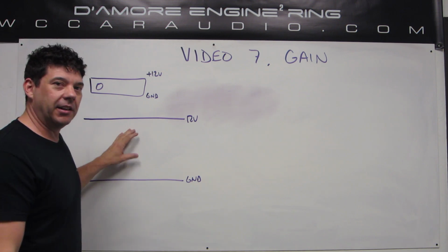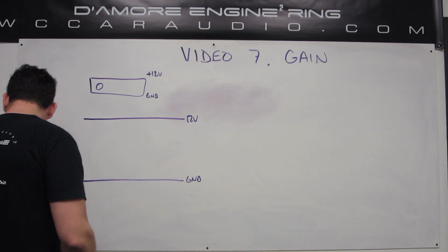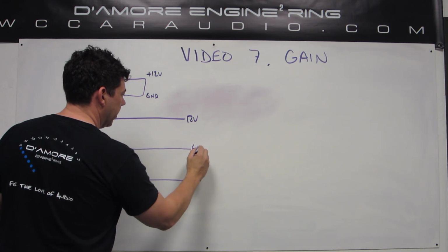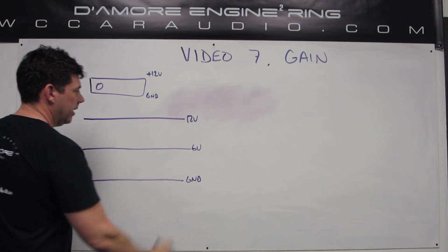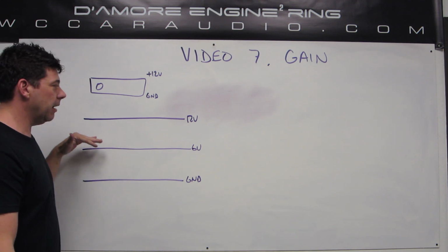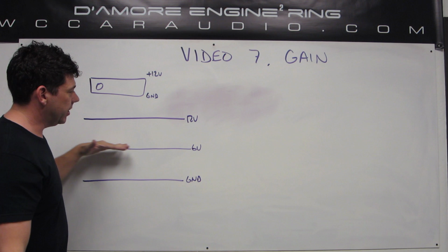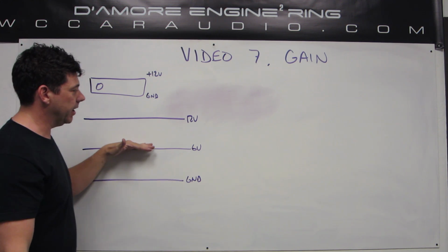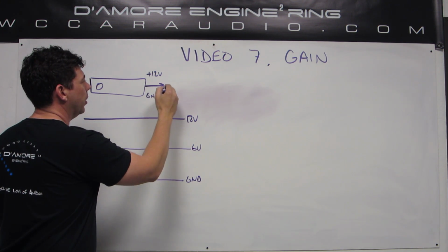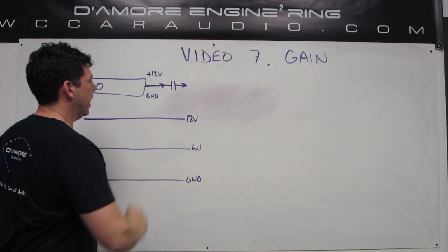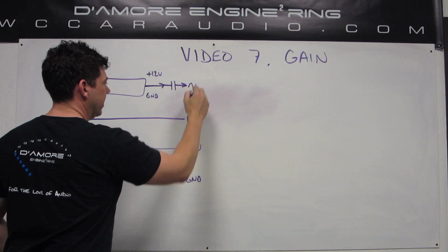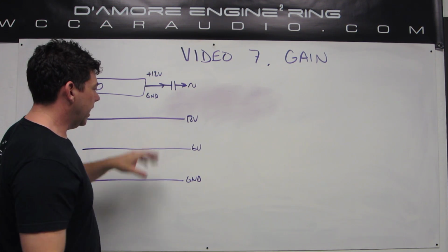Well, the head unit doesn't have a negative voltage, so what happens is we bias the audio signal up so that it's halfway in between the rails, halfway in the middle. So 6 volts. So inside the head unit there's some biasing that takes the audio signal and lifts it to here, so when there's nothing coming out of the head unit, the volume's all the way down, it just has this 6 volts DC where the signal would be. It doesn't come out the RCAs because at the end, if this was the actual output, they put a capacitor here, and capacitors block DC. So it would block all the 6 volts out, and the only thing you would get is the AC voltage coming out of there. But inside the head unit, this is what's going on.